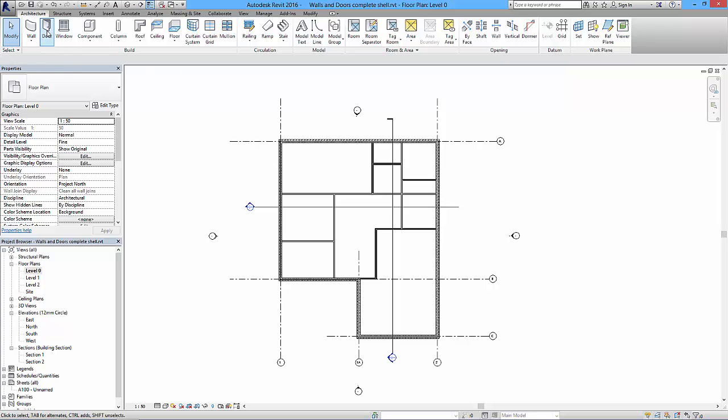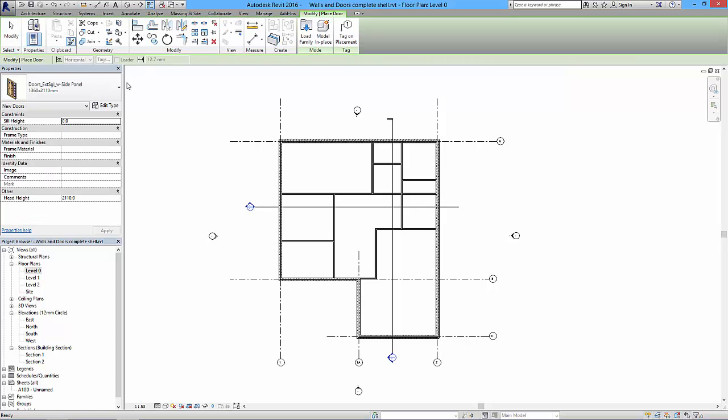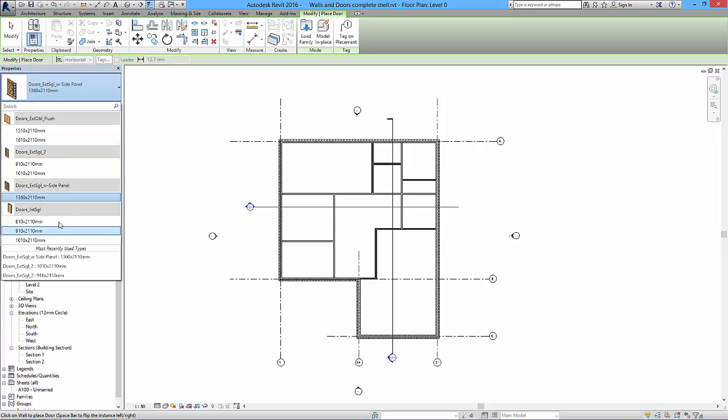So we go to doors, start off with doors, and we click on door. And I've hit the drop down. You might not get all these options simply because I've loaded up a few others. Now you can't click on this grey bit, but it's these white bits underneath that give us the types of door. We've got this external double door flush. Now we've got external single number 2. We've got external single with a panel. So how do we get all these into the system? And we've got internal doors there.